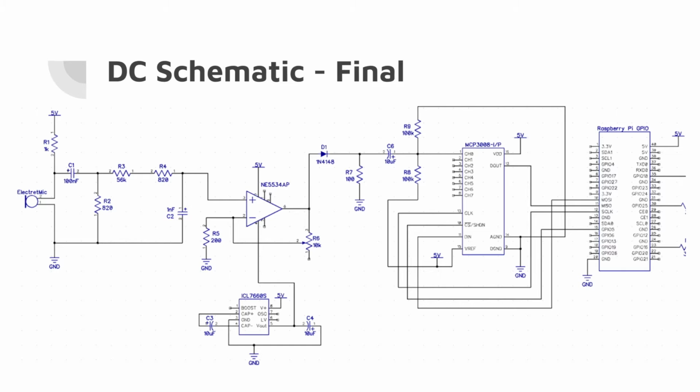On the left, you can see our sensor, the electret microphone, the RC bandpass filter, the op-amp, and the R6, which is the potentiometer, which is configured as a feedback resistor for sensitivity adjustment. The analog signal goes to the voltage divider, which is then converted by the ADC chip and sends a signal to the Raspberry Pi.